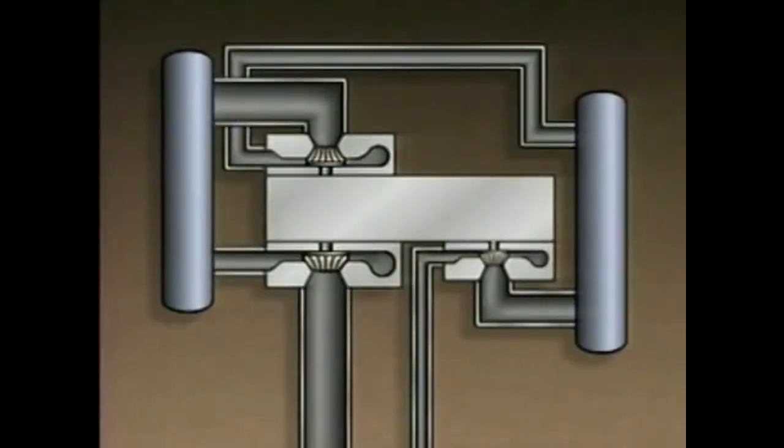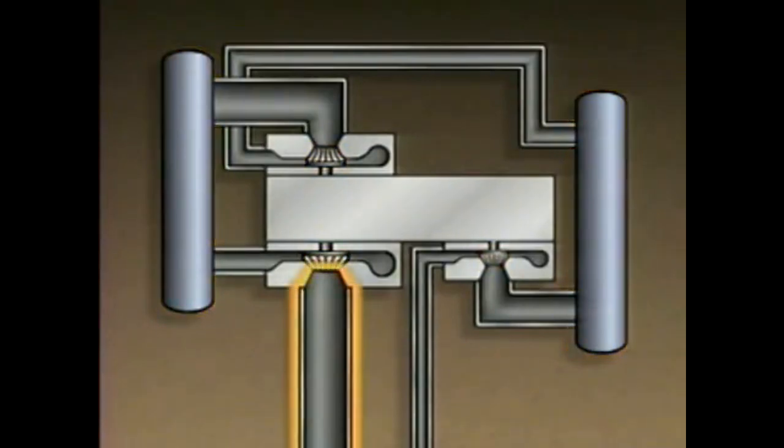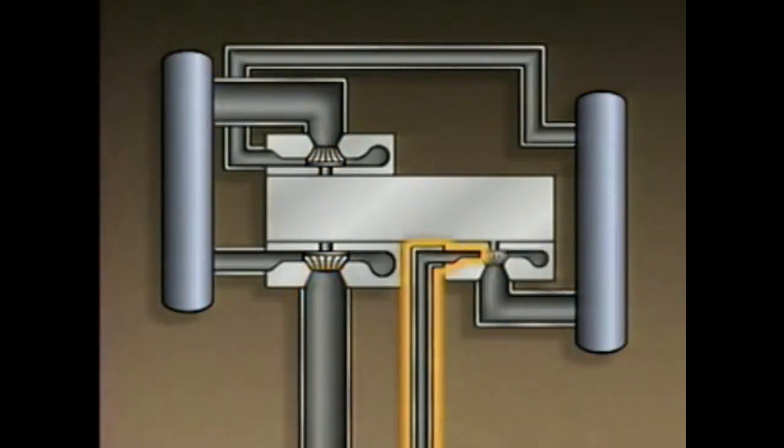In general, single-stage centrifugal compressors produce fairly high gas flow rates, but their discharge pressures are relatively low. In systems that require higher discharge pressures, multi-stage centrifugal compressors are typically used. This simplified illustration is a top view of a multi-stage centrifugal compressor. The compressor has 3 impellers, 2 intercoolers, a suction line, and a discharge line. There is a volute associated with each impeller.